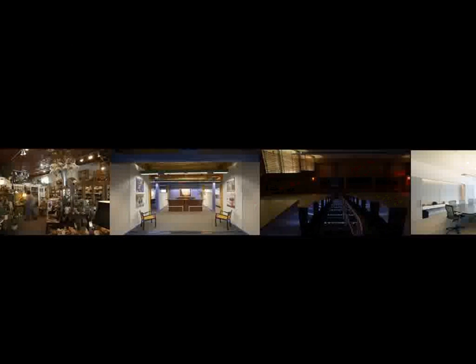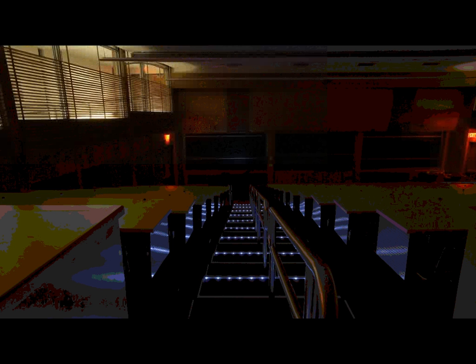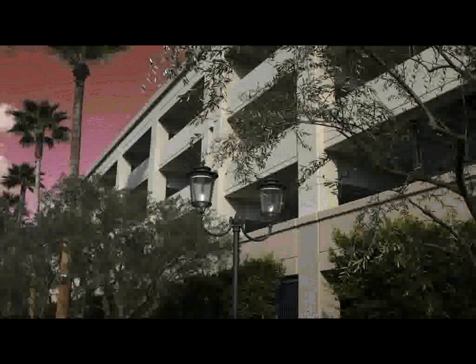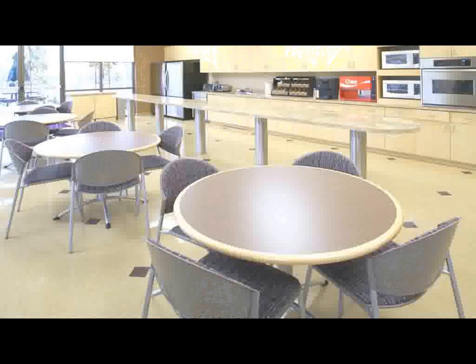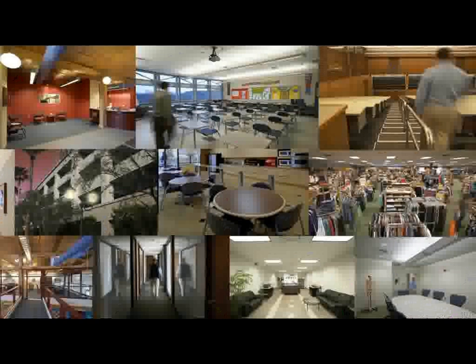Other control scenarios that can be incorporated into profiles include after-hours activation or deactivation of an occupancy sensor's dual technology detection, scheduled daily and seasonal adjustments of photocell setpoints, dynamic schedule control of the exterior lighting, and selective dimming or overriding off of lights for load shedding. The combinations are endless.